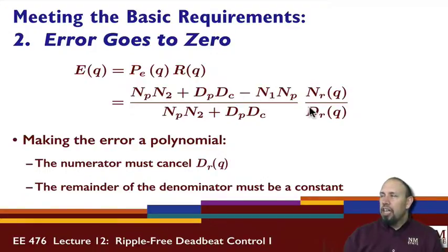And it's not a problem that you're canceling this in this case because, well, as long as we're not trying to track a signal that's blowing up. Okay? If we're tracking a signal that's persistent, like a step input, or a sinusoid that just has constant amplitude but doesn't decay to 0, then we're good. So that's actually an okay cancellation.